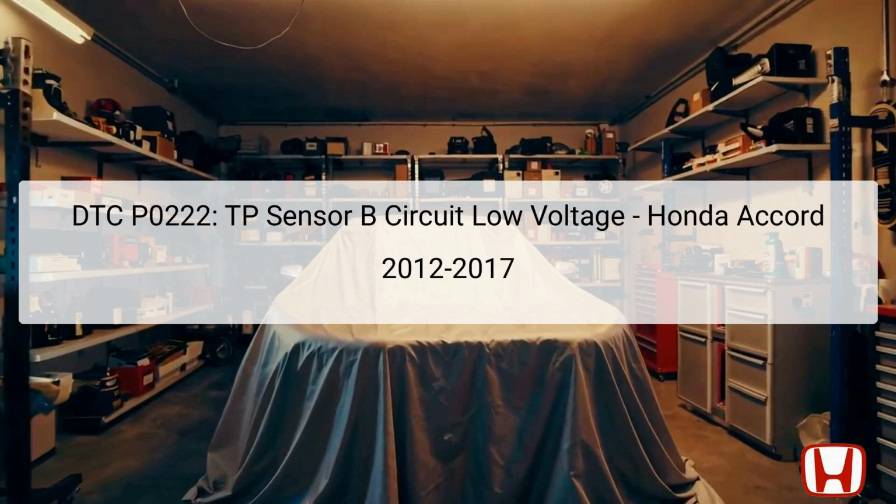The throttle position sensor plays a critical role in determining how much air enters the engine, directly affecting performance and emissions. DTC P0222 is triggered when the voltage reading from TP sensor B falls below an acceptable threshold, specifically under 0.3 volts. It's essential to conduct a thorough diagnostic to pinpoint the exact cause and make necessary repairs.